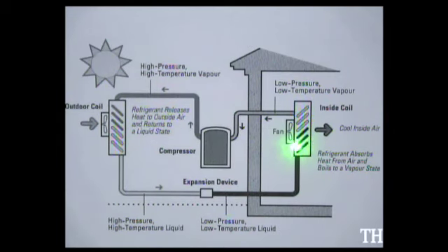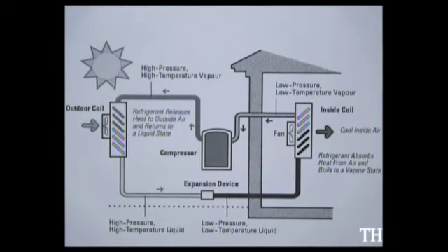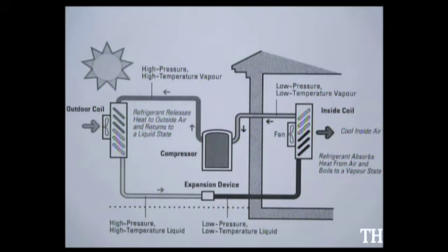Then down below this A coil in your air handling unit, you'll have a drip pan. And this drip pan will then have a pipe that flows underground outside your home to drain this water. Just remember, an air conditioner is only a mechanical device that collects heat from an undesirable location and conveys it to a more desirable location, namely from inside the house to outside the house.